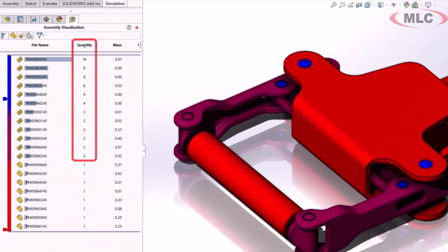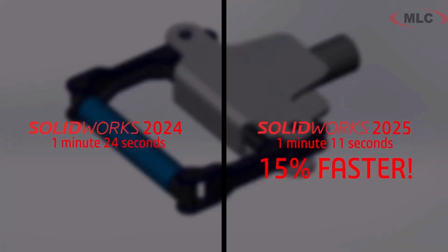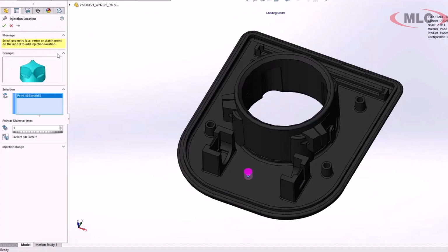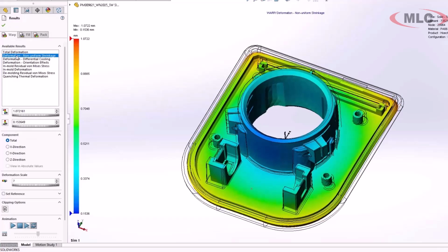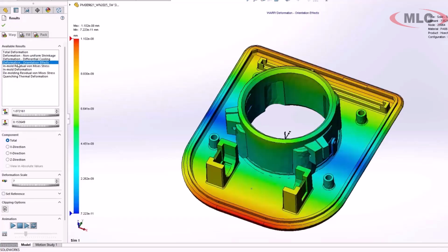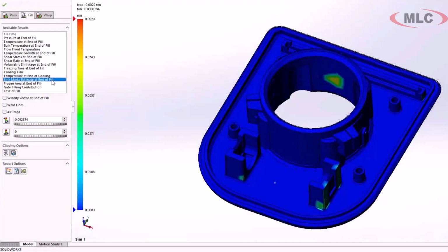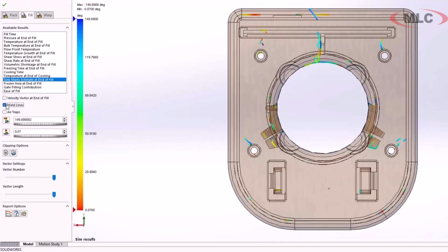As you know, we must mesh the study in order to get results. In 2025, parts mesh up to 15% faster when using the blended curvature-based mesher. Finally, we'll switch to simulating injection molding for plastics. In order to make sure your parts turn out exactly as expected, you can analyze the warpage displacement by viewing the unbalanced cooling, orientation, and non-shrinkage events. As for sink events, a new and more accurate solver is used to ensure your injection molded parts turn out just how you modeled them.